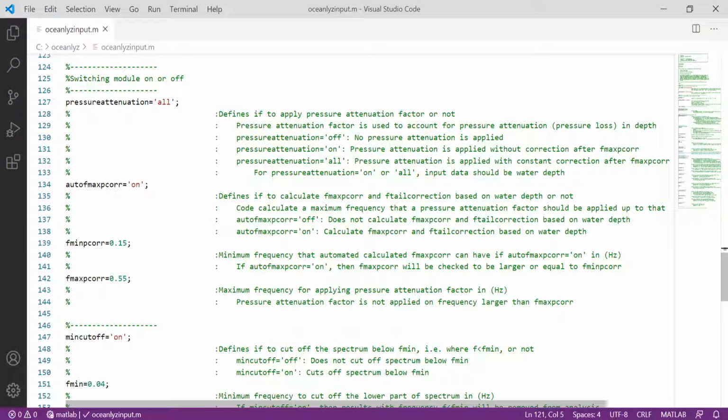If you measure the water depth with the pressure sensor, the problem is that the energy dissipates in the water depth. So when we put the pressure sensor 1 meter or 2 meters beneath the water, some of the energy from the surface wave will be dissipated, it will vanish before it reaches the sensor. So whatever the sensor reads is less than the actual energy on the surface, and because of that we have to compensate for the energy loss in the water column. So this is how we do that.